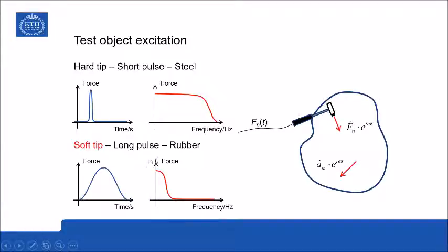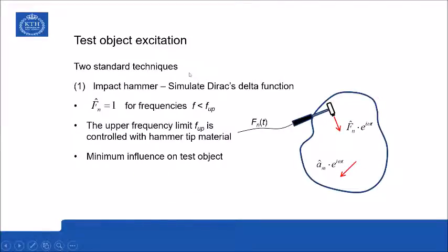So a rubber tip would be preferable if we are only interested in a fairly low frequency range. Then it's a waste of time to go for a wider frequency range as we can get with a steel tip.